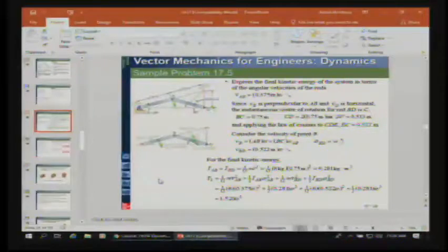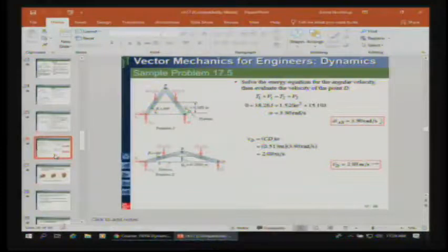This gets a little bit more complicated just because of the geometry, because of the trig. I wouldn't put anything that hard on an exam, I want to make that really clear. But basically what we're still saying is that we're getting those components of the velocities at those particular times, and we're equating them to a translation and a rotation. So A is just rotating, and D is possibly doing both, but the sum of those things is going to be purely horizontal. Once you get your geometry worked out, you can come up with an omega, and then you can come up with a VD.